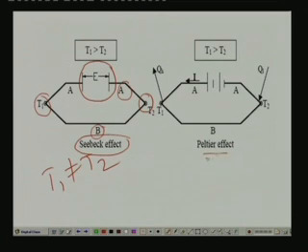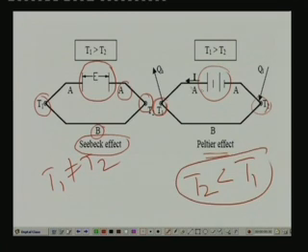Now the Peltier effect, this is the reverse of Seebeck effect. Okay, Peltier effect is reverse Seebeck effect. Here what we do is, initially the two junctions are at the same temperature, then we connect a voltage supply and pass current through this. So when a current passes through these two dissimilar materials, you find that at the junctions the temperatures will become different. So in this case you will find that T2 is lower than T1. Okay, so as long as the current is flowing through it, you will find that there is a temperature difference. So as a result, at T2 you can get refrigeration effect and heat rejection takes place at T1. Okay, so this is known as Peltier effect.